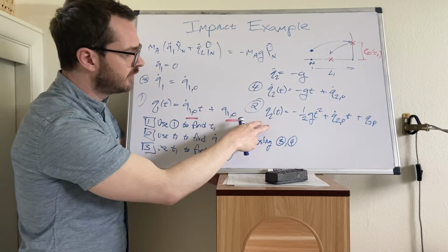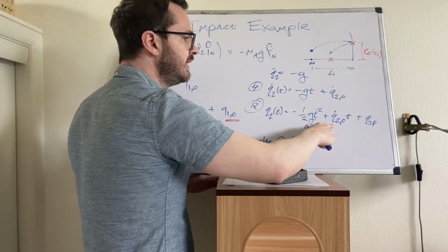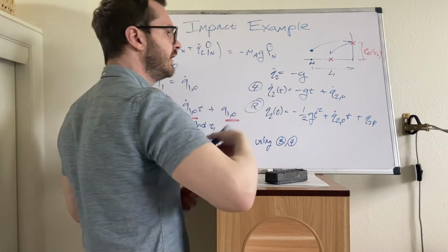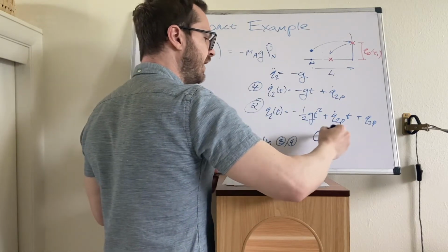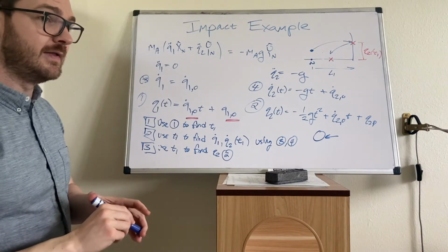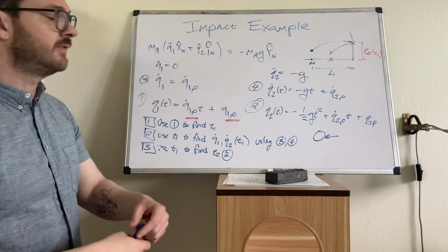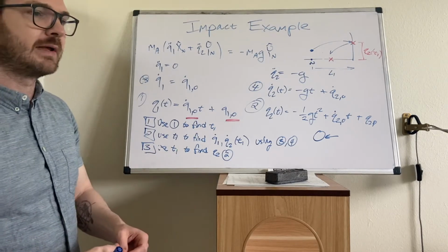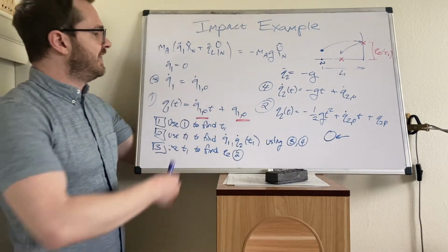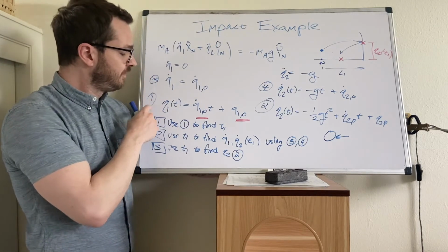And then the initial values for Q2 will change. We will be at a new height, right? And then the speed will actually remain unchanged. Consider that, we'll see this in a bit, but the free body diagram on the ball has restitution and compression forces only in the x hat in direction. In an actual impact, yes, it would affect other things, but that analysis gets more complicated and you can go to graduate school and study it. So the setup then for the second ballistic phase, same questions.